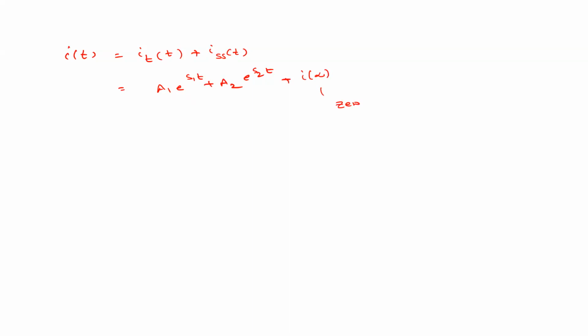When we have a series RLC circuit, we managed to find the current value, right? In the parallel RLC circuit, we found the voltage across the capacitor. So ultimately we can generalize the things. Whether it is current or voltage, the ultimate expression is transient plus steady state value.